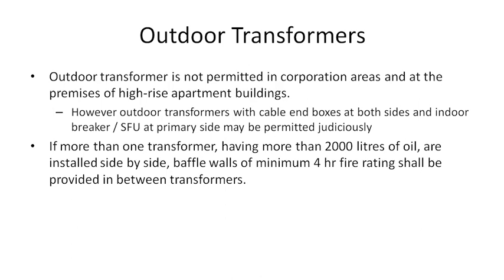Now if we go to corporation areas, you can see outdoor transformers, but our regulations say that is not allowed. However, outdoor transformers with cables and boxes on both sides and an indoor breaker or SFU at the primary side may be permitted judiciously, it also says. So even without these, we see transformers in many places on our roads. But that is, in fact, a violation of this particular clause.